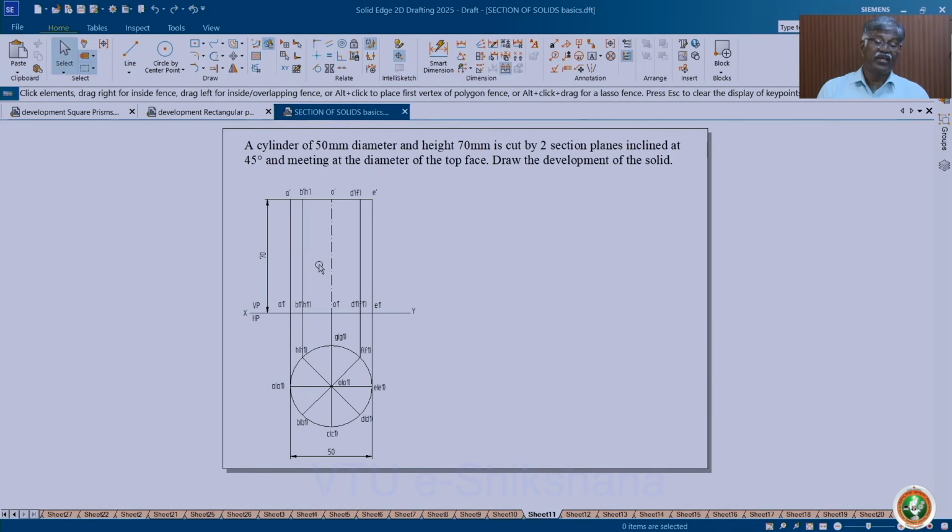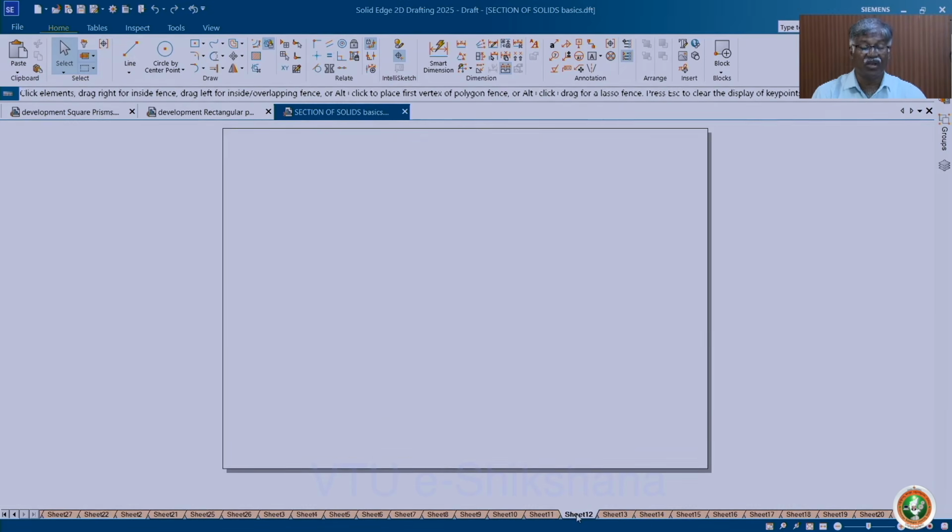Then comes the circle with the height, that is nothing but cylinder. Okay. If I cut parallel to the base, then you will get the circle only as the section as well as true shape. Suppose that if you cut the generators and inclined, then you will get definitely true shape as ellipse, the top view section is circle only. Okay. Then that we will discuss at later stages.